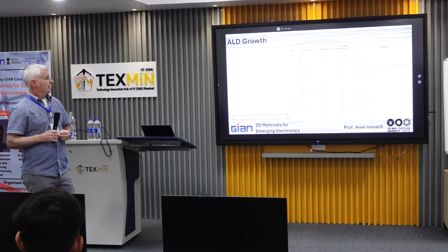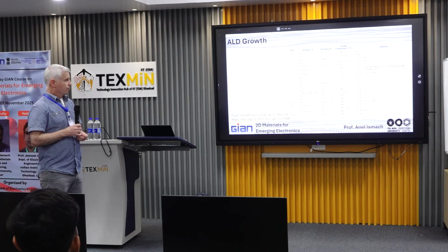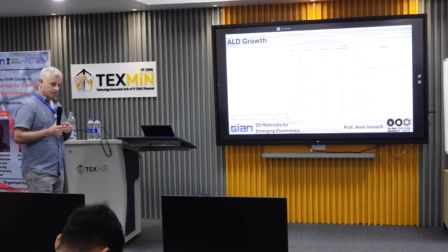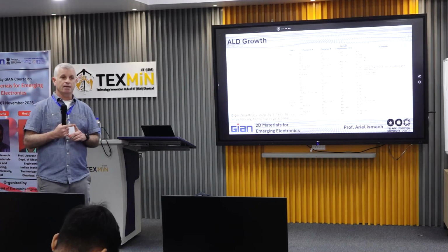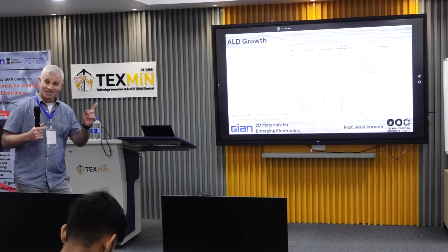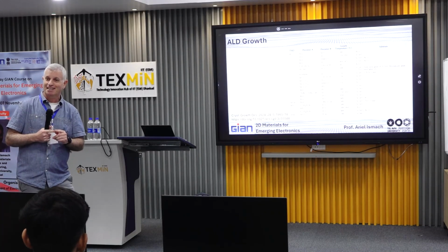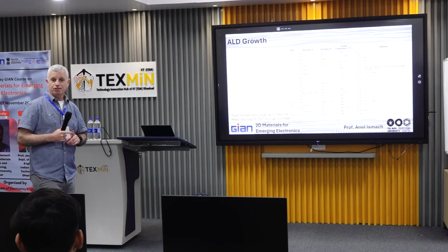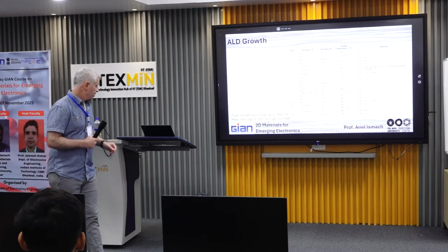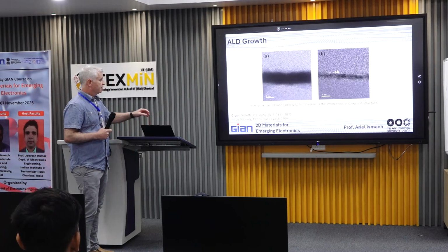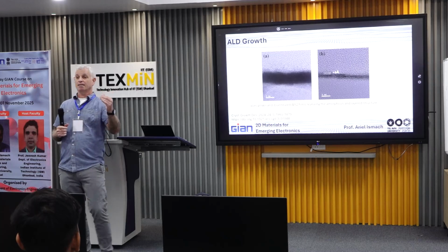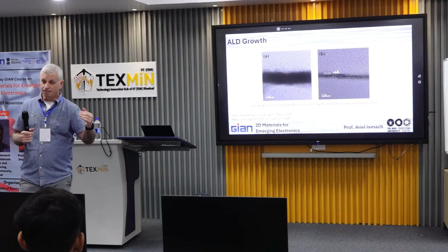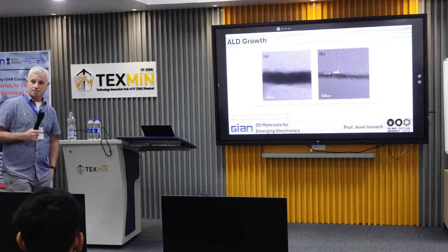For trying, you can grow, of course, but the crystallinity will be rather low. And also, in atomic layer deposition it's very hard to control the atomic layer number. I didn't see any result in ALD showing a single layer formation. Usually after the ALD, in order to improve the crystallinity of the layer, you need to do some annealing process.